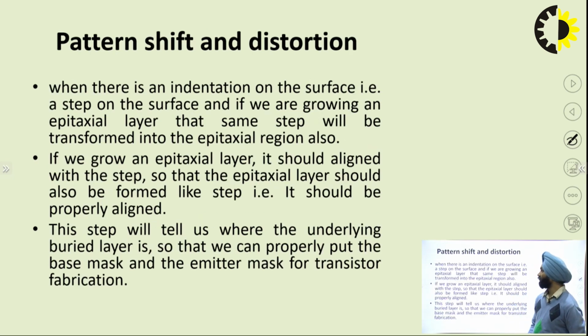The pattern shift is when there is an indentation of the surface, that is a step on the surface, and if we grow an epitaxial layer over it, the step will be transformed into the epitaxial layer.